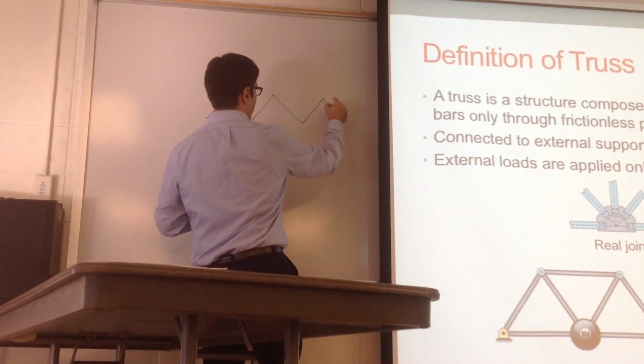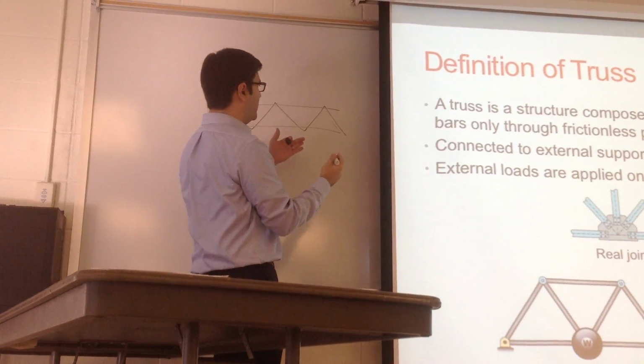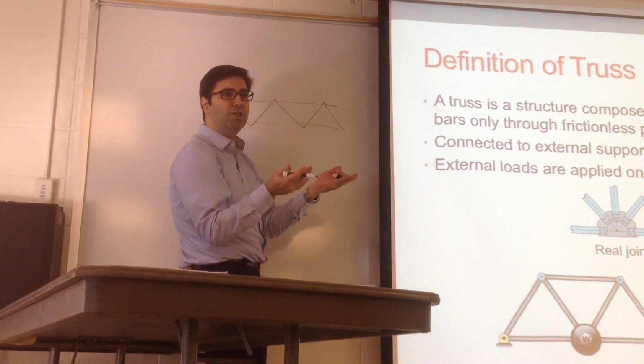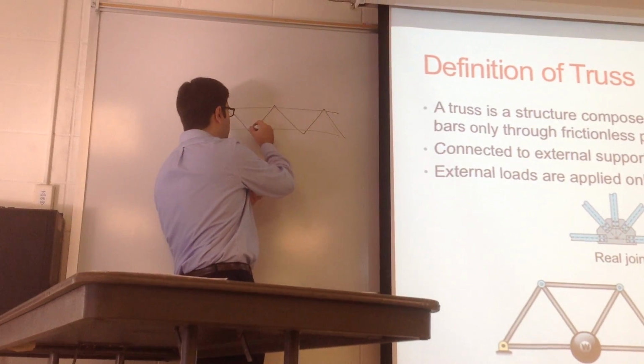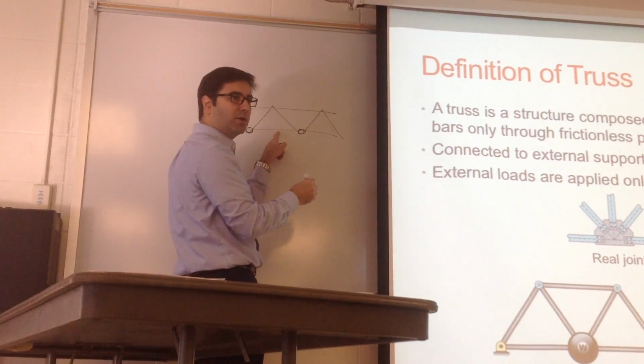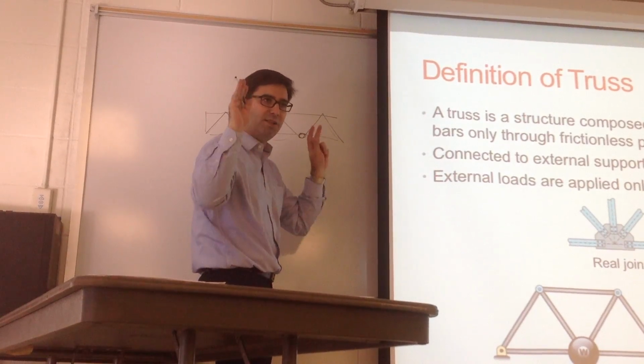Yeah. So let's say this is a structure in a wing spar. It's a truss structure. So you have to pick the point to attach the engine on the wing. Okay, so you will attach the engine, let's say here and here. You will never attach the engine here, because if you put a weight here, this guy will start bending and no longer works as a truss.